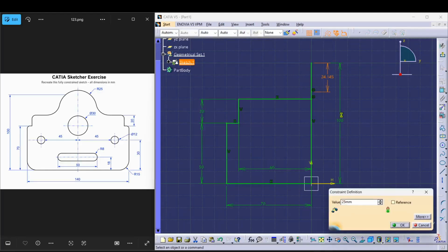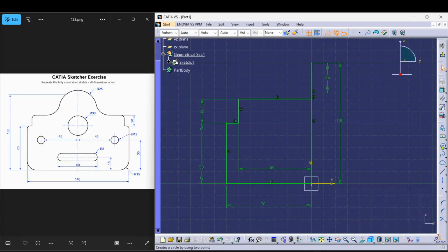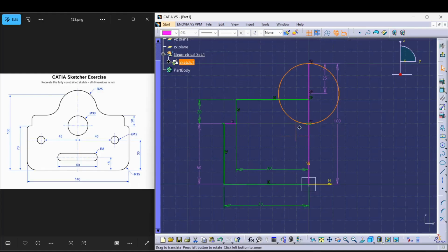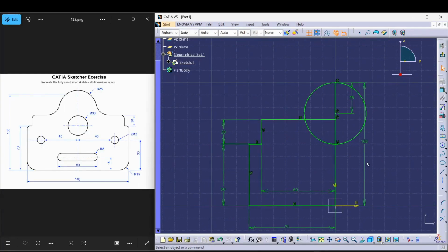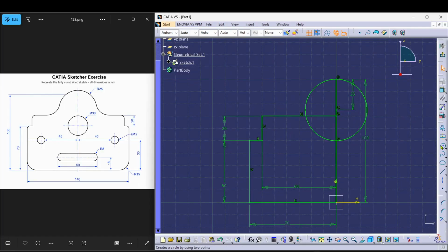Please make sure the reference geometries are construction elements only. If not, then use the Construction tool to do so. As you can see, by mistake, we've made this sketch over-constrained. Green color is for iso-constraining, and pink is for over-constraining. So whenever you see this happen, check for the exact cause of the over-constraint and then correct it.